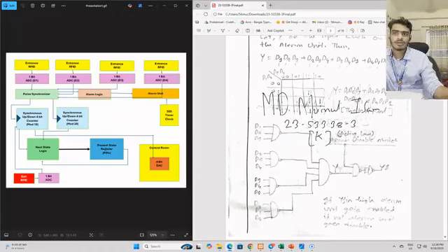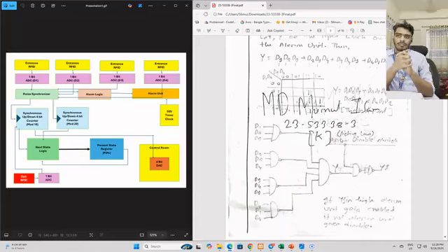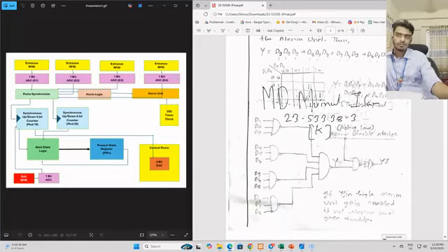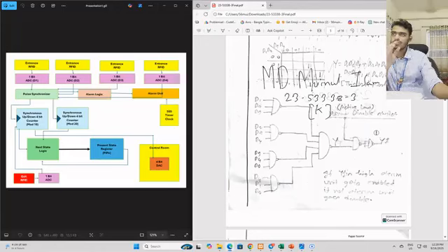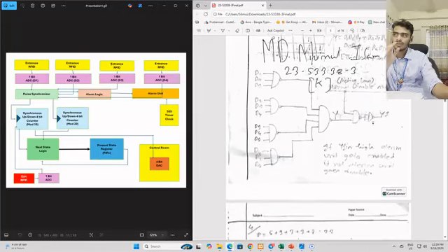If you press this button, the whole alarm should turn off. And remember, this is an active low button, so I designed it with a NAND gate. So that goes our alarm logic unit.